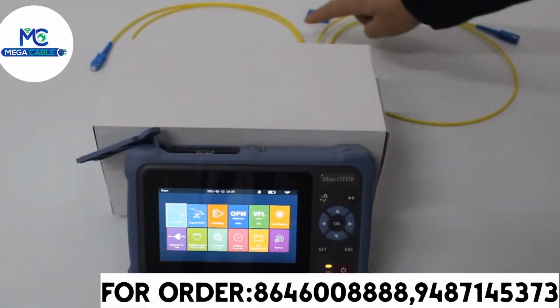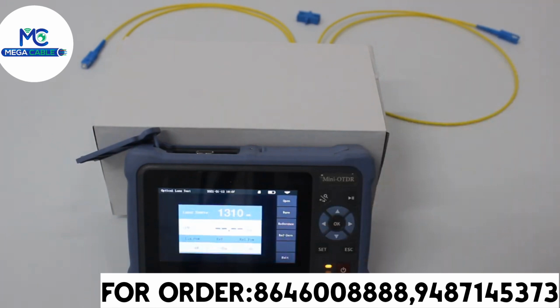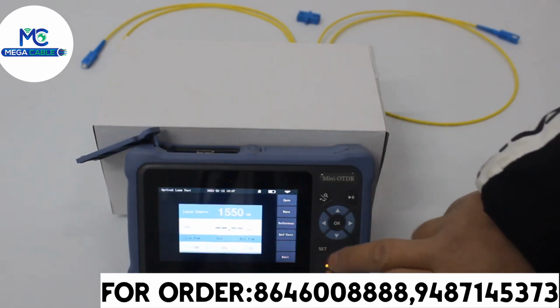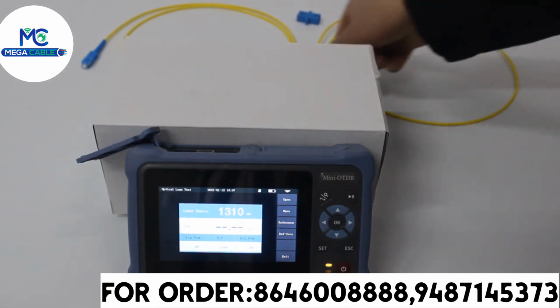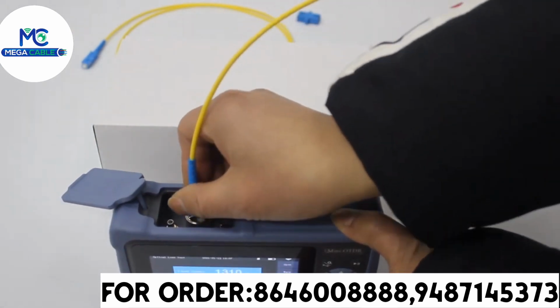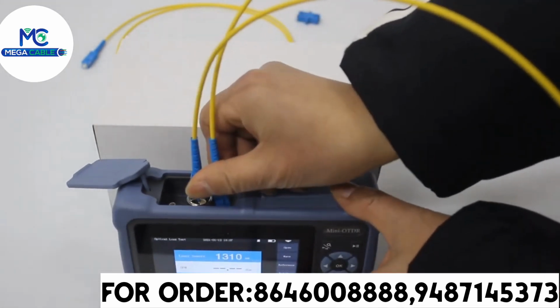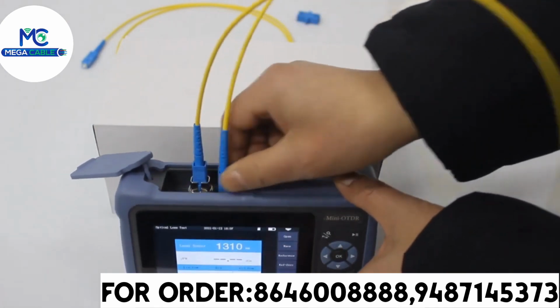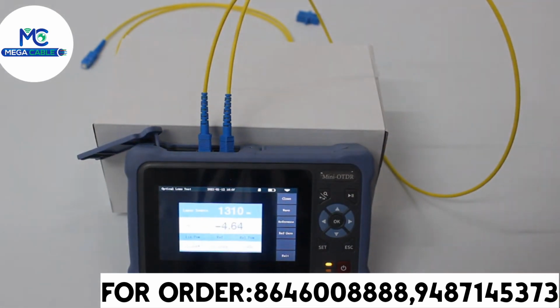This is the reference patch cord, the patch cord on test, and the SC adapter. Click Optic Loss Test. Click Wave to select wavelength 1550, 1310. We select 1310. Insert reference patch cord into OTDR AOS port and the OPM port. Click Open. The optic power is minus 4.62 dBm.